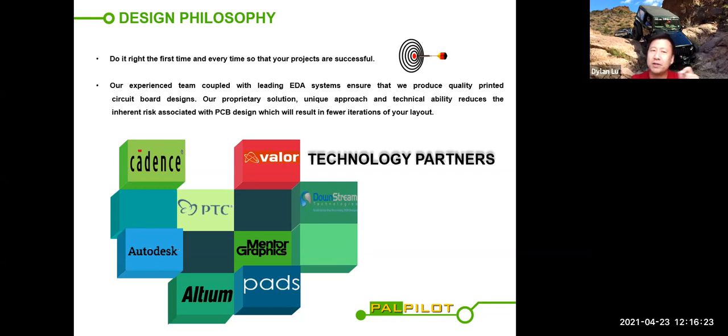The reason it's called computer-aided design is because we need that computer to help us. When you do high-speed signals, when you do controlled impedance, you will have a lot of rules and topologies that you need to follow. If the board has signal integrity or power integrity requirements, you have a different engineer doing all the simulations and then giving you all these parameters to follow.